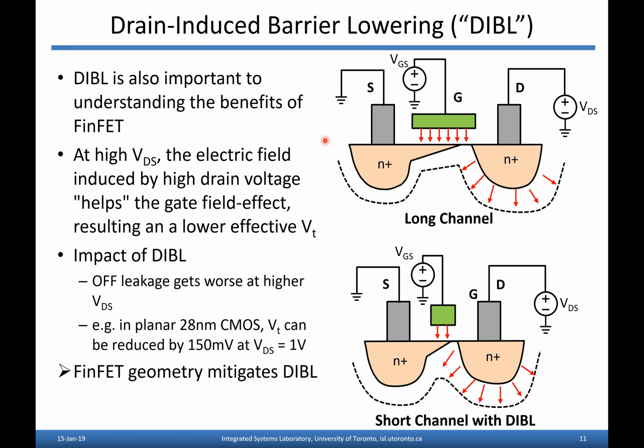We won't go into all the physics of it. It's quite difficult to model. But I think hopefully we can understand it qualitatively just from these cartoons here. So the idea is, here's a planar MOSFET pictured here that's turned on. So there's a positive VGS applied for an NMOS transistor. Channel's inverted, and there's also a large VDS applied.